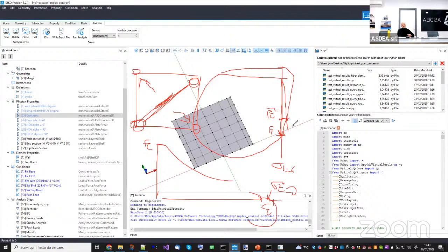Actually, something that the truss model cannot capture is that they do not include the increase in compression under biaxial strain. They should do something like this, for example. If the transverse deformation is negative, I should increase it up to a certain value. So basically, the effect of the transverse deformation is taken into account by the yield surface. The problem is that since they didn't have a yield surface, because it was a truss model, they invented this stuff, okay? So that thing is taken into account already by the surface.